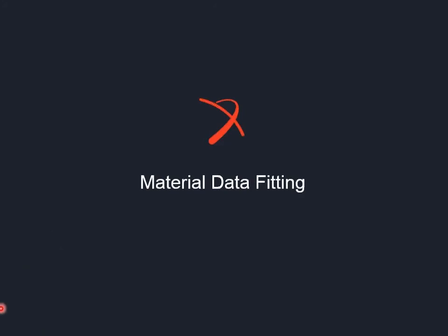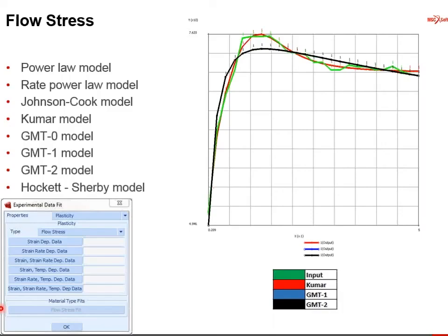I mean, we started with material curve fitting for rate-independent rubber materials, Mooney, Rivlin, and Ogden. And then we added more material data fitting associated with viscoelasticity and viscoelasticity for harmonic analysis, the so-called Payne effect. And now we've added additional material data fitting for 3 types of models.